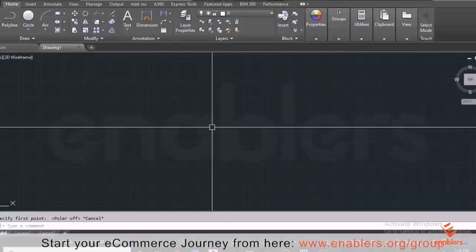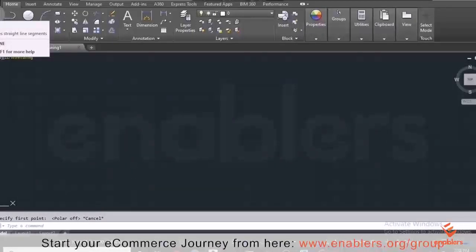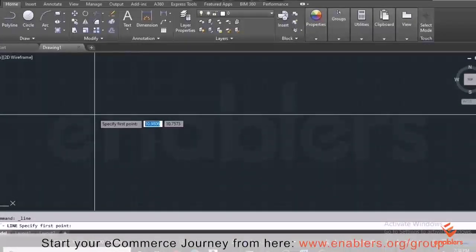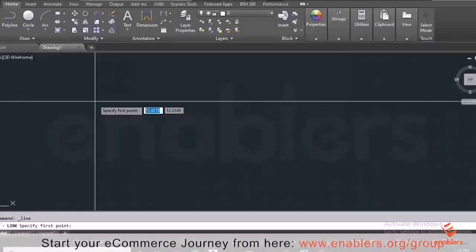Okay, let's start our very first drawing quickly. For that we have to go to the line tool and click on it. Now you see that after activating the command, we have two intersecting lines; this type of cursor is called point cursor. Right next to the cursor, you will see this kind of bar called dynamic input toolbar. If you don't have it, that's fine. You can bring it using the F12 function, and also you can make it disappear with the same function. Right now I am not using this bar, so I will make it disappear.